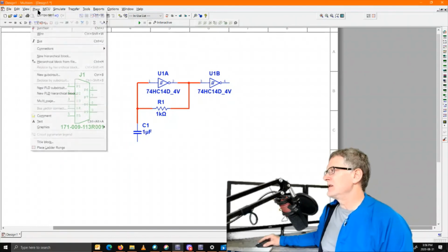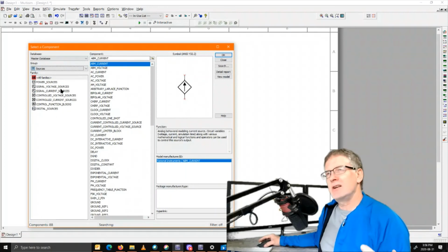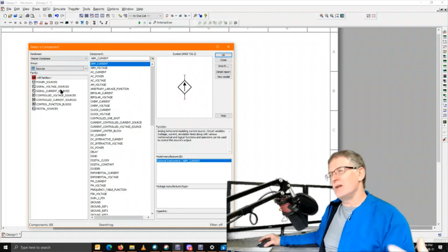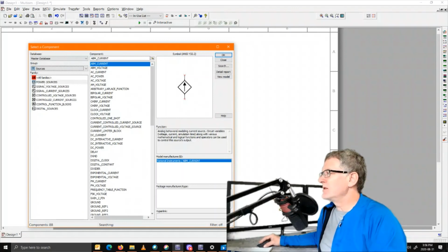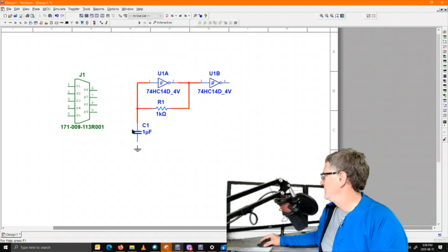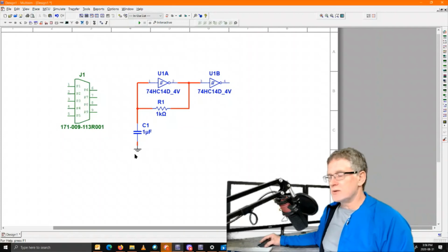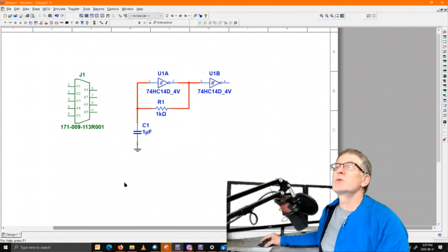Another kind of part that I can place from the database, so let's go back to the sources, is parts or objects that have no footprint associated with them. For example, on a power source, I can put in the ground symbol, and I can connect that to ground. So there's a ground terminal connection, but a ground doesn't really have a part on a board. It's one of the traces, but it's not a separate physical part that I would buy. It comes with the circuit board.